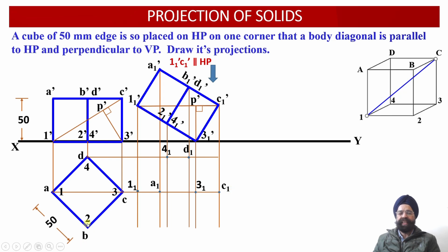And finally, these are the last 2 points, that is 2 and B. So once we draw the horizontal line through the points 2 and B, let us evaluate the intersection of this horizontal line with the vertical projector lines drawn through the points B1 dash and 2-1 dash. So this is our point B1 dash. From B1 dash, we draw the vertical projector line.